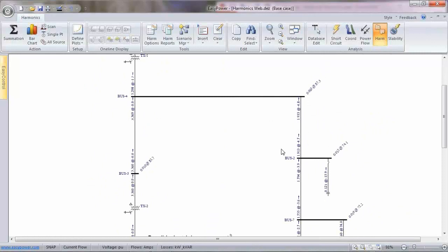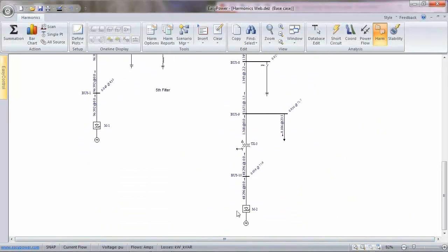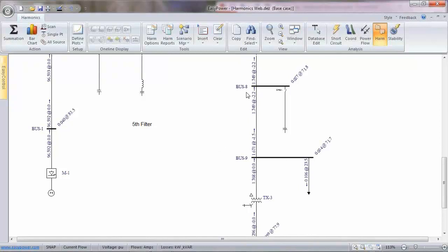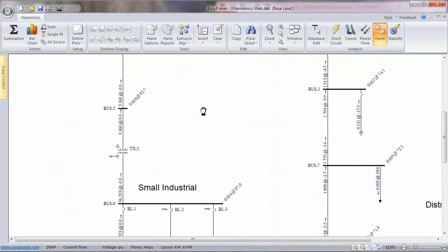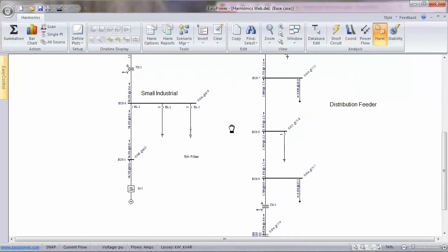So the other amount of 5th harmonic is being produced by this drive down here. It's got 48 amps of 5th harmonic, and it flows up through the system. And it goes through the conversion of the turns ratio through the transformer and finally makes it up here and sums. Now, these sum linearly mostly because I specified my injections.